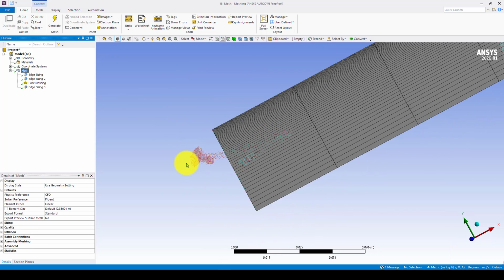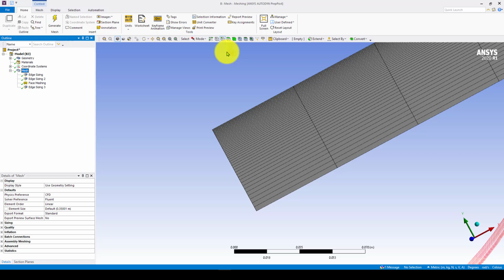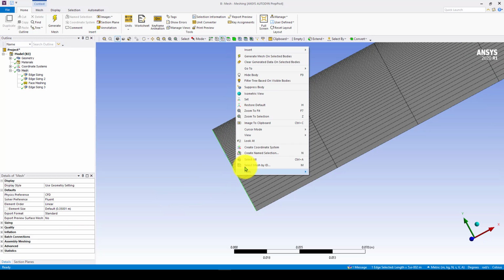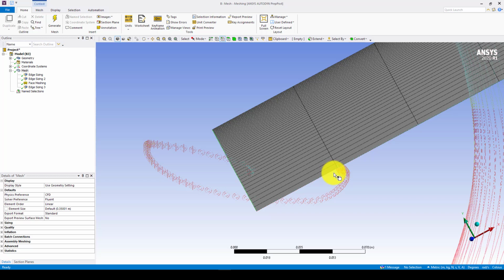And now the next step before moving to Fluent is that we need to select the edges or surfaces where we're going to assign boundary conditions. Here you can select volume, faces, an edge, or a point. So we're selecting edges here. You click here, see that it's green. Right click now, and here you have create name selection. So I will call it inlet,